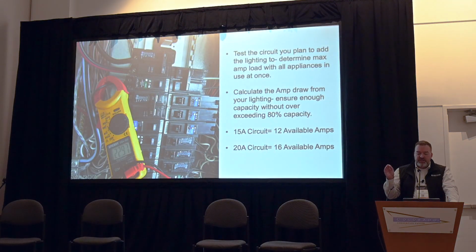One thing he's also going to do, and I'd recommend you guys do this when you're out installing your lighting, is know what circuit it's going on, especially if you're not using a dedicated circuit for landscape lighting. You don't know what's on there. I've had times where we or a tech plugged into a circuit and thought, hey, this is good to go. Then the customer comes in and they've got all these appliances in the garage, and it overloads the GFI, and it just keeps tripping the transformer because of an overload.